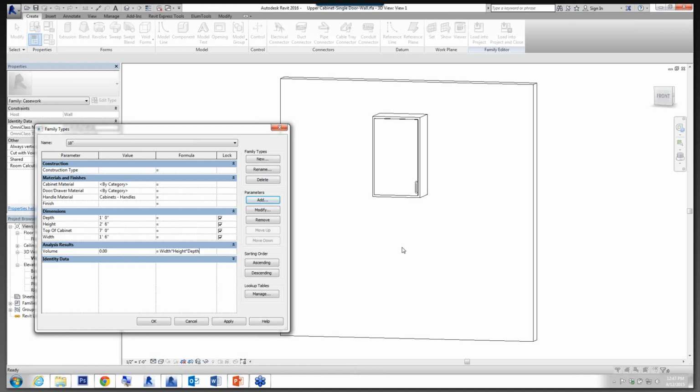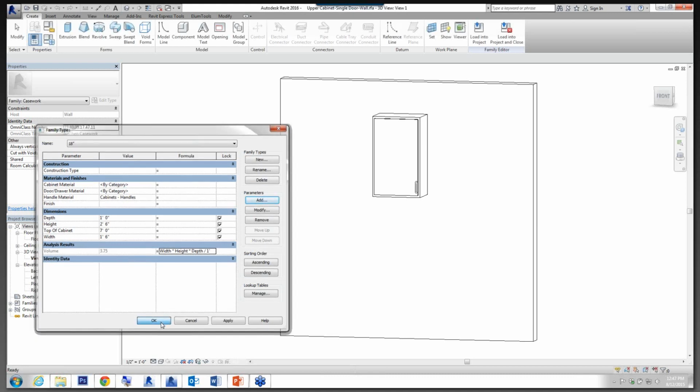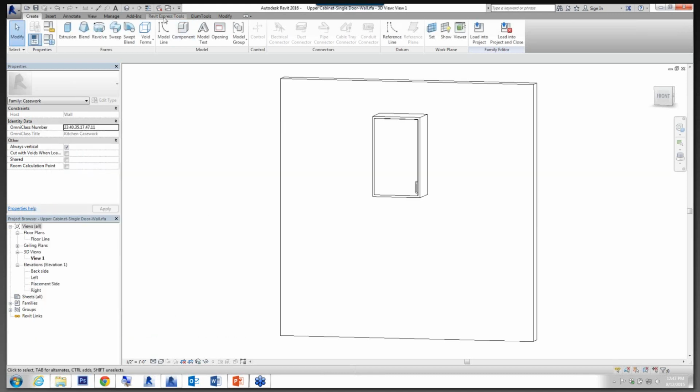And then divided by 1 foot, so we don't create a problem. So with this unique parameter that also happens to have a formula, I'm going to use the Revit family processor to push this parameter into a whole bunch of other families. And one family won't have one of these values, like depth, for example. So in that family, it'll still make the parameter, but then the formula won't exist. And it'll show us an error that that wasn't able to be done.